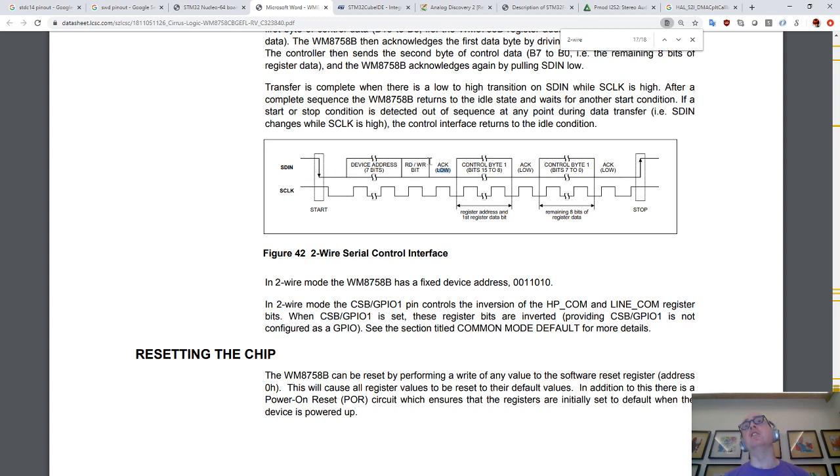switch the data line to a read, and then I actually set them up as open drain outputs so that they can only pull it down, and then I use an internal pull up of the chip so that I'm not fighting the codec. So I skipped that bit, but basically you configure the SDA line as an output, open drain only, with a pull up resistor, which is 20K, which is too high, but then we're going to do it really slowly.